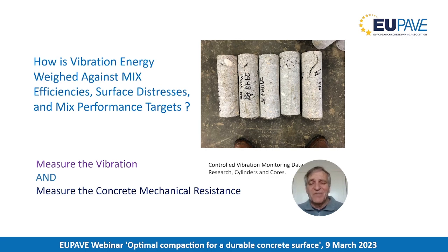Basically, if you control your vibration, it has an impact on your mix, and sometimes you can get more efficiencies out of that mix if you don't have to put more micro air in it because vibration is taking it out, or paste, because you're having paste issues, volume issues. So getting vibration frequency and energy in sync with what the resistance of the concrete is really important. And that's why we always preach, and what we work for in carbon neutrality is, measure the vibration and measure the concrete